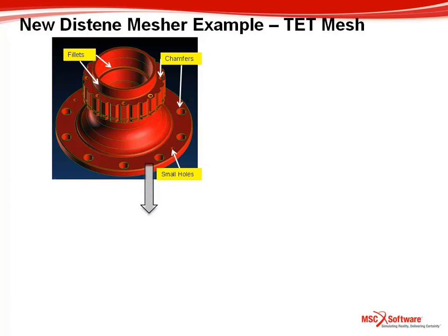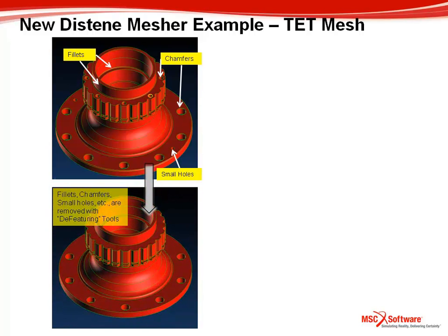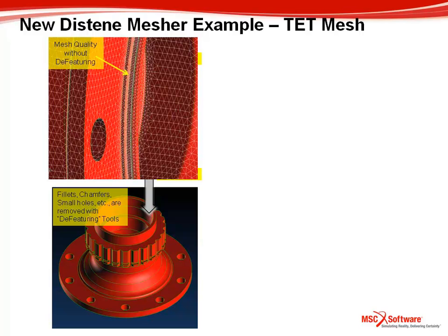The next step I'm doing is going through some of the CAD defeaturing tools and removing some of the small holes, fillets, and chamfers to generate a cleaner geometry that I need to mesh.